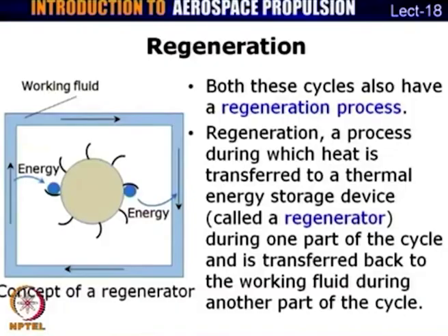Regeneration, as we have just understood, basically involves transfer of energy to a thermal storage during one part of the cycle and transfer of that energy back to the working fluid during another part of the cycle. So, with this in mind, regeneration enables a cycle to have isothermal heat addition and isothermal heat rejection, which is required if you want to have efficiencies which are close to that of the Carnot cycle efficiency.